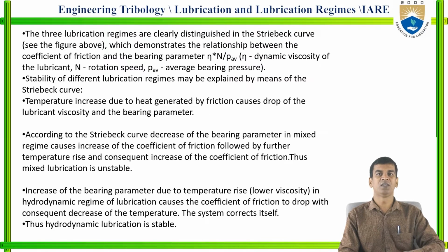Now we will see the increase in bearing parameter due to temperature rise in the hydrodynamic regime of lubrication. It causes the coefficient of friction to drop, with a consequent decrease of temperature. The system corrects itself. Thus, hydrodynamic lubrication is stable.